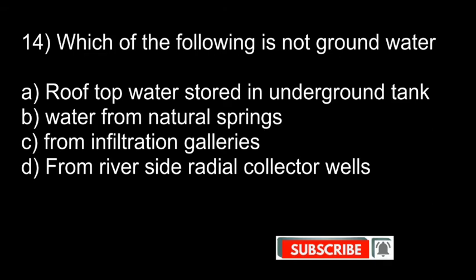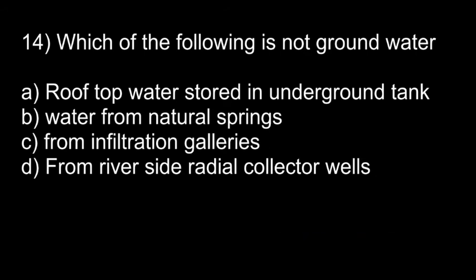So the water stored on the rooftop is considered as a surface source of water, whether it is in an underground reservoir or storage tank, etc. Surface water has suspended impurities, hence it is not considered safe for water supply without necessary treatment. That is why it is considered a surface source of water. Here, our answer is option A, because rooftop water stored in an underground tank is considered surface water because it cannot be used for drinking purposes unless it is properly treated.